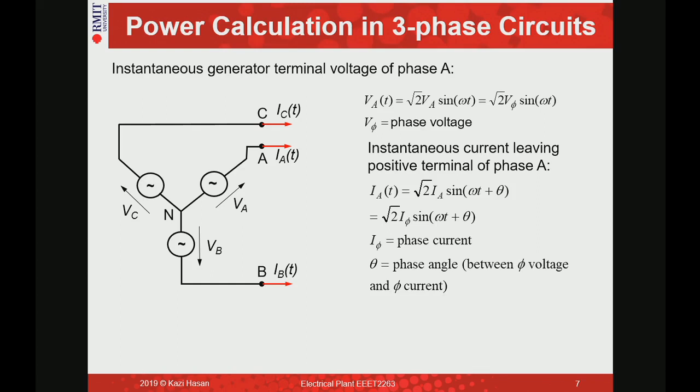If you start by saying that you want to use the cos function, that is fine as well. It doesn't have to be √2 Vp sine omega t; it can be cos omega t. So now we have voltage and current, and both are phase voltage and phase current. For Y connected, phase current and line current are the same, but phase voltage and line voltage are not the same. So we will consider that later.